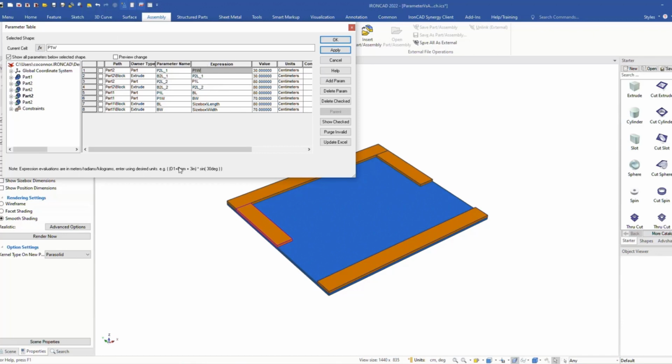However, these are actually 7 centimeters here, so we need to subtract this distance here, because it's going to go all the way. If I type it in there, it'll actually overhang. So you'll see this, if I hit apply, it'll actually overhang that geometry. So we need to subtract some information here. Those are 7 centimeters, so we'll just times it by 2, or just type in 14 centimeters inside of there in this case, and now we've got those aligned. So now we hit OK.